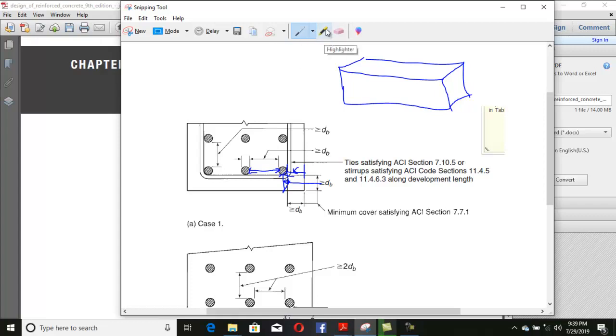I design steel bars in this beam, and let's say I design one bar for this beam for a certain loading. Then I design this beam at the yielding stress of this steel, that is Fy. We are taking it as 60 ksi or 40 ksi. Let's say this is 60 ksi. If I design this steel through its yielding stress, that is 60 ksi.